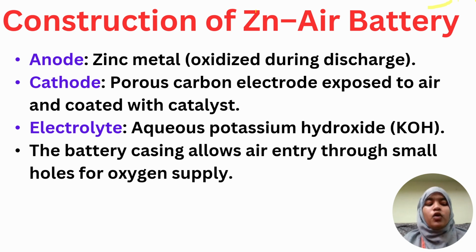Here the anode is a porous mass of zinc particles. The cathode is an air electrode with a catalytic layer to facilitate the oxygen reduction reaction and a gas diffusion layer. The electrolyte is an alkaline solution like KOH. Here we are also using a separator, that is, a porous separator that keeps the anode and cathode from touching while allowing ions to pass through.